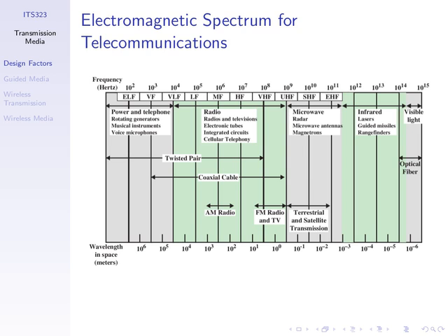When your receiver is tuned in to listen to this channel, it's receiving this signal plus any of the small leftover signal from this channel, because it may not be down to zero yet. But because this one is the strongest, we can receive and understand what this signal is. So even if there's a small amount of energy coming from this transmitter, this one's much stronger than this. So we consider this noise, and this is the signal strength. If the signal strength of what we want to receive is much larger than the noise, we can successfully receive.